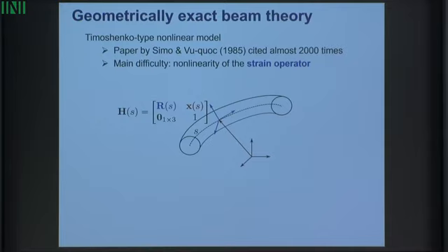So the first step to get the strain is to compute the gradient of this field of matrices, and we represent the gradient as we did for the velocities. And we have this gradient here. It's a skew-symmetric matrix in the Lie algebra, F tilde. And then the question is, what is the relationship between this gradient and the strain?